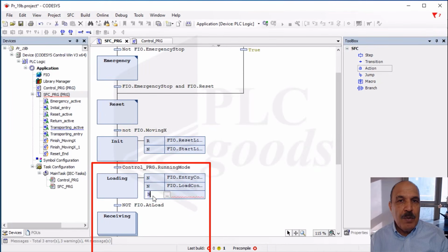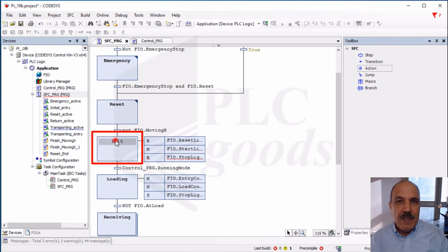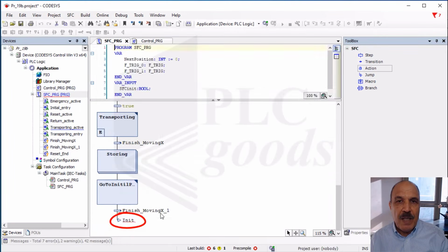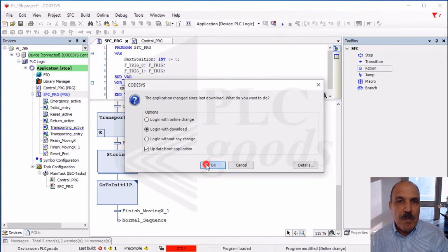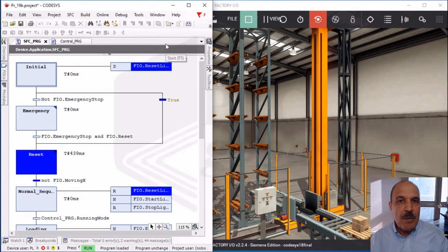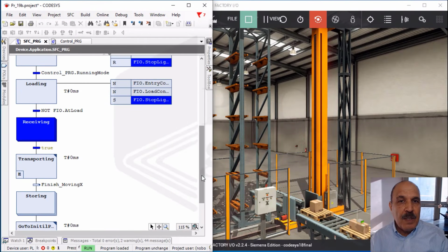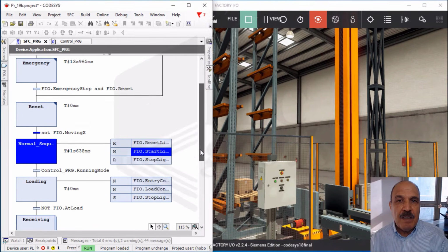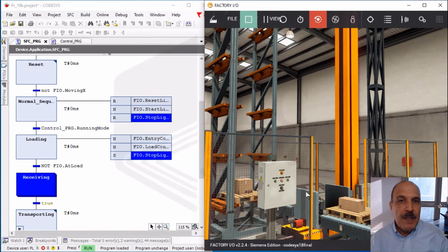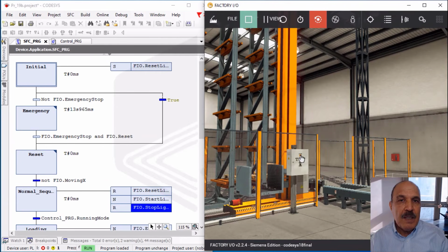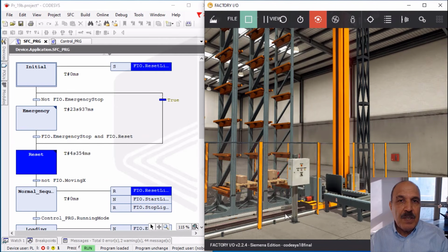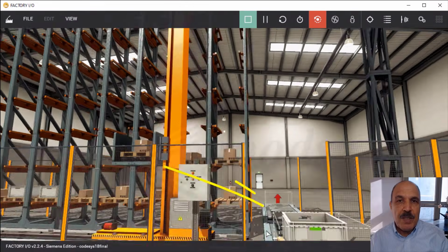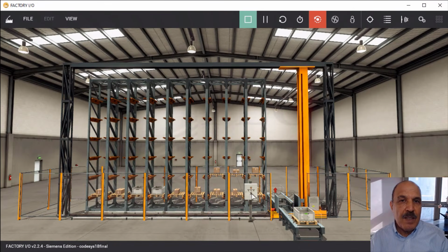A new POU is created to manage these conditions using a flag and jump instructions for controlled program flow. The tutorial concludes with testing the project, highlighting its sensitivity to emergency and reset inputs, and it suggests the potential for extending the project to collect additional sequences.